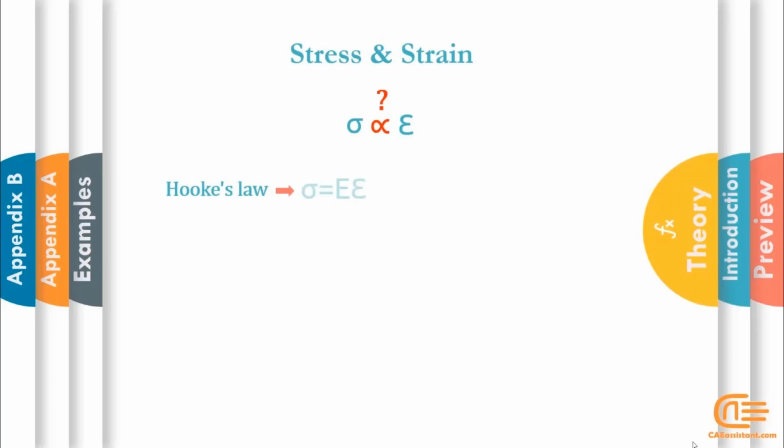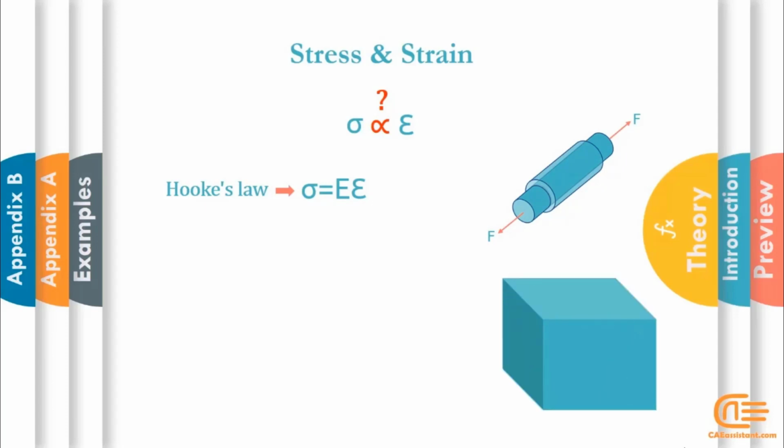Well, if we go back to a few previous slides, we said that to determine the relation between stress and strain, Hooke's law is one of the most usable models. According to the law, stress and strain for elastic materials have a linear relation, and the Young modulus coefficient determines this relation. Consider a rod of elastic material that's subjected to axial load. Its tensile stress is linearly proportional to its fractional extension or strain by the modulus of elasticity. This relation is a simplified type of stress and strain in one direction and in the form of a scalar.